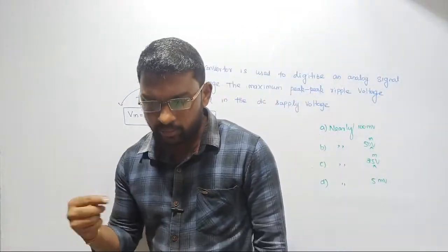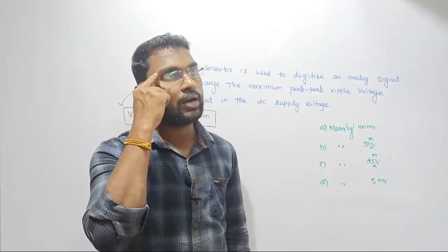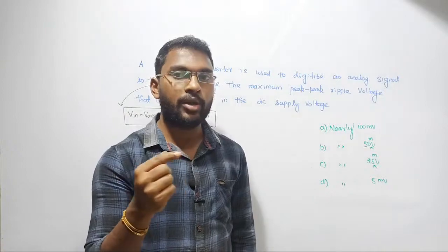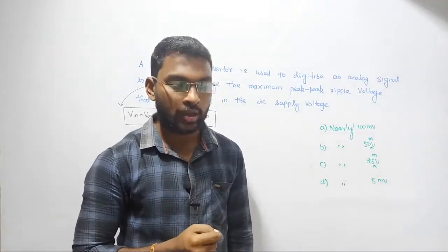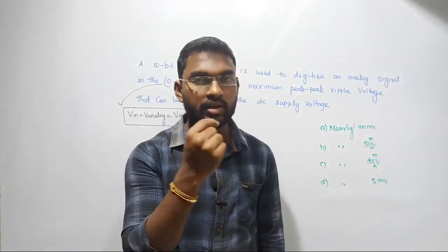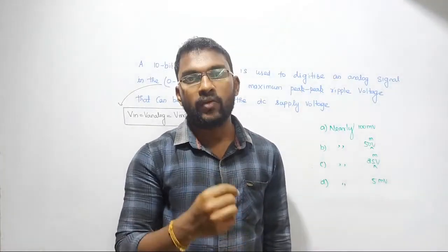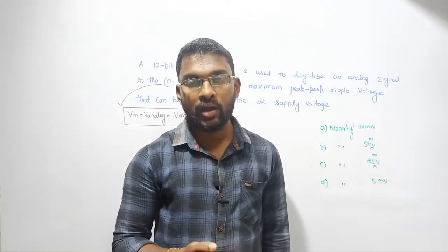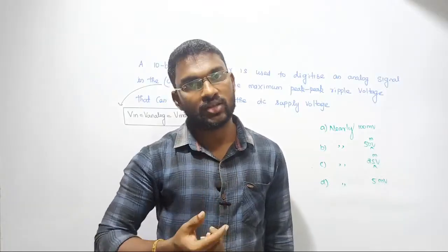So when we allow the maximum voltage, we immediately need to think about what happens inside the circuit when the input voltage is applied. Immediately we need to think about the resolution, right? Yesterday we saw the basics. Resolution is what first comes to your mind. Resolution means step size, how many staircase steps we are going to consider. We need to consider step size, or 1 LSB, or resolution. I am repeating once again, you need to think in terms of step size, right?